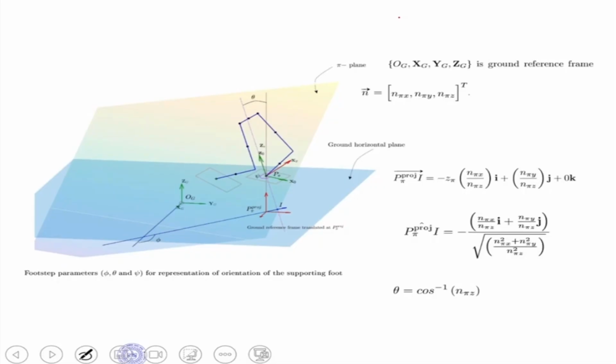We said that when a biped robot walks on flat ground, there are infinite trajectories which are possible. There is a leg trajectory and a hip trajectory, and in the last class we looked at how to optimize the leg trajectory and the hip trajectory and minimize the torque, where energy is equal to tau into d theta dt. So this is the total energy that is being consumed, and based on that we find the leg trajectory which is best. Now let us look at a little more tricky situation, which we have discussed in the last class also.